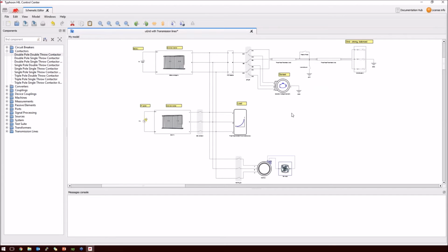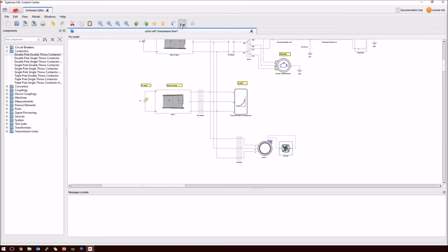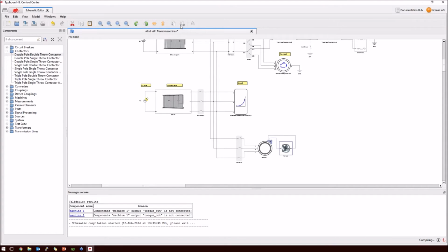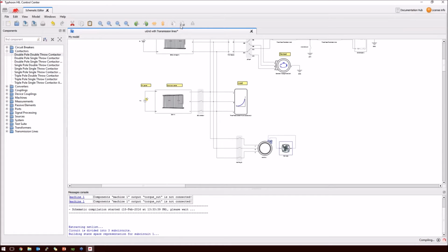Okay, great. So I'm going to go ahead and start compiling this and give you guys a feel for how the compilation process looks. We are compiling to an FPGA on the HIL, but this is not going to take hours or days. We're compiling a softcore that's pushed to the unit, so it's in a matter of minutes. So that really gives you the capability to go in and tune your model properly and not have to worry about crazy long compilation times.